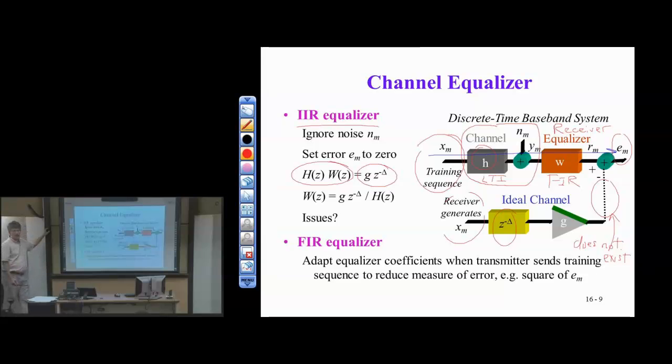Well, this one's not bad. If I know the transfer function of the LTI component of the channel, then I can just divide both sides by that to get the equalizer transfer function, and from there I can get the coefficients. So for example, if H of Z were FIR, then H of Z would go in the denominator. So the zeros in the channel become the poles in the equalizer. See any problems with that one?